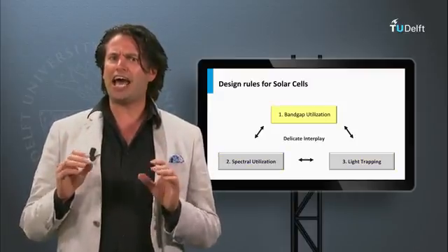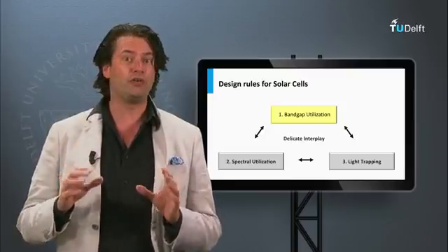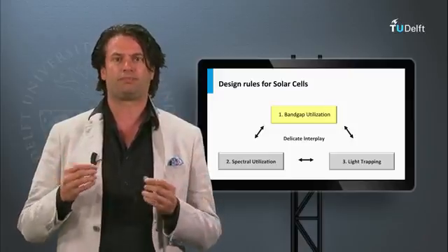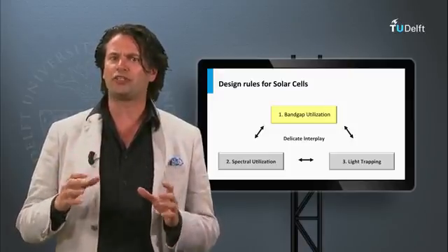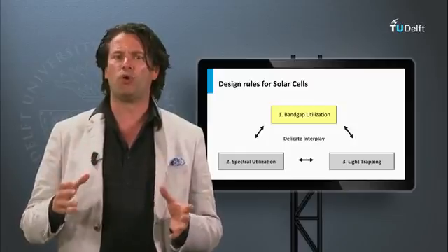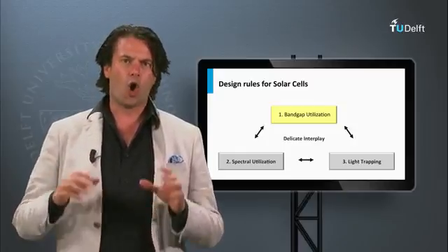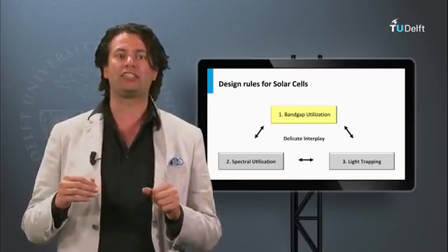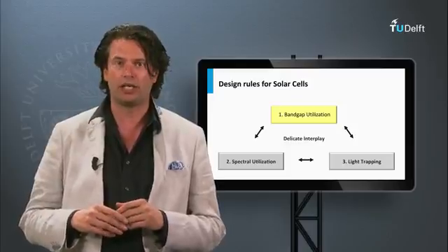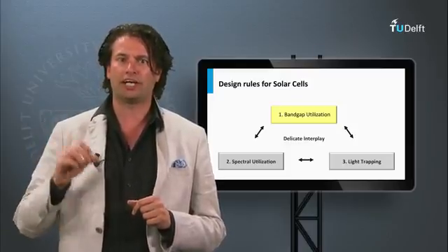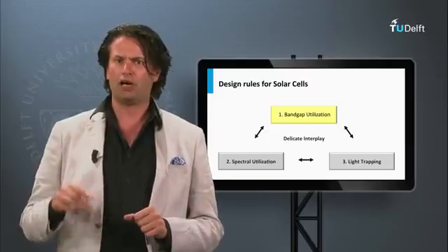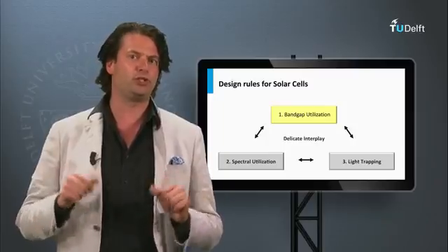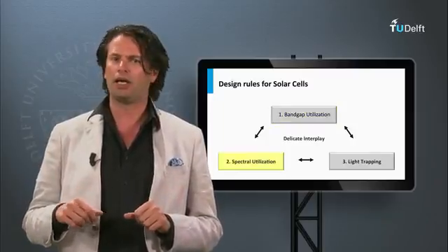First, the real energy used to generate voltage is the product of the open circuit voltage and the elementary charge. Under normal operation condition, this energy is always smaller than the total bandgap energy. Open circuit voltage is determined by the extent to which the quasi-Fermi levels are able to split, which is limited by the charge carrier recombination mechanisms. We will show that the various PV materials have different recombination mechanisms that limit the utilization of the bandgap energy.